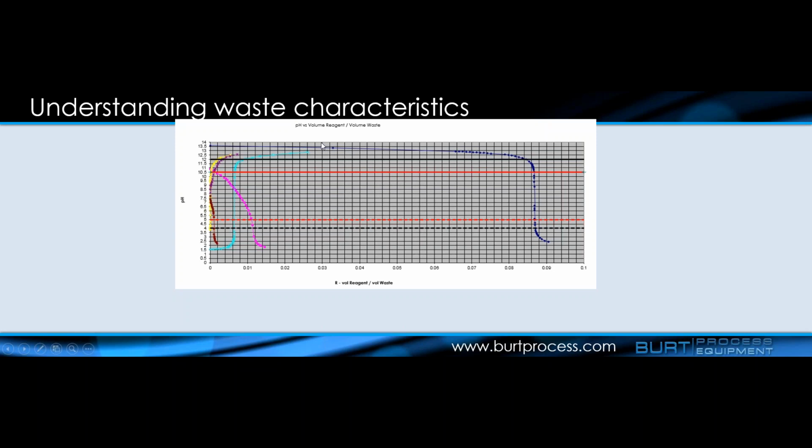When you're doing boiler cleaning, they tend to buffer way up here in the pH 13 range. So what happens in those situations, which is shown on this chart here, is you would get a very linear curve because your chemistry is reacting with the buffers in that range, and then it would just drop like a rock because you don't actually have enough chemistry there. You're just reacting with buffers at that point.